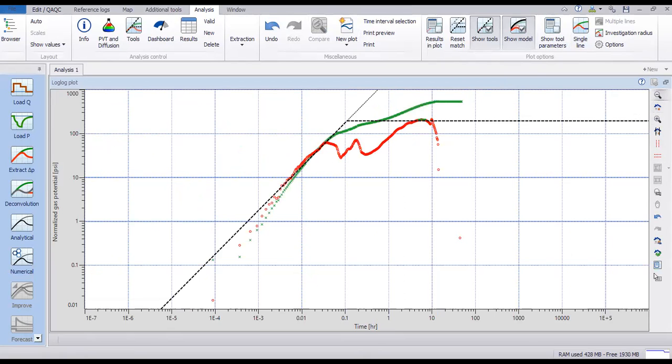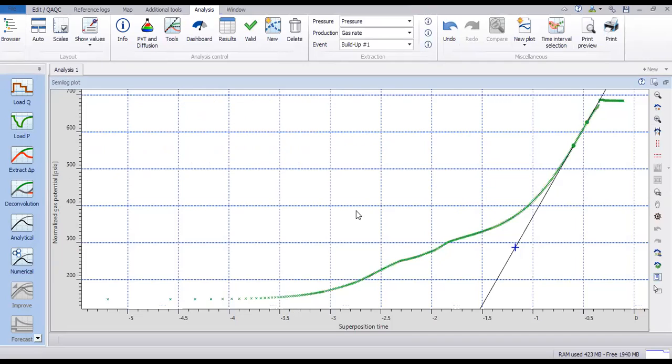So if I minimize this one on the semi-log plot, I get the slope, the line overlaid here, which is quite reasonable if we want to estimate our permeability from this one, because the shape is quite difficult, okay? And you know that in semi-log analysis, we need to get the permeability from the straight line, assuming that in that straight line, our radial flow occurs, okay?